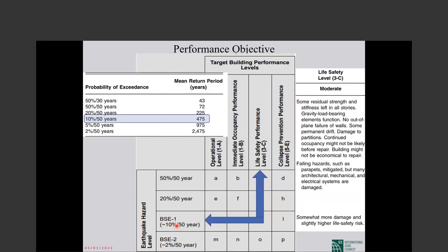No, in performance-based design, you don't need a prescriptive importance factor. For example, if your building is important, you can say, I want life safety instead of this level of earthquake, under this level of earthquake. So explicitly, you can select what you want from this building.